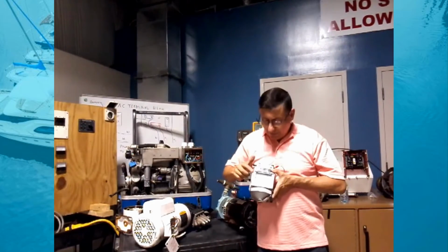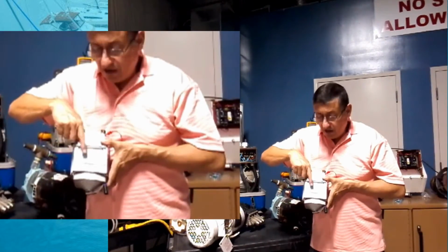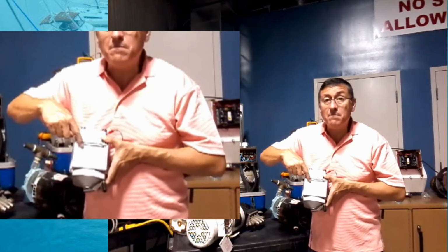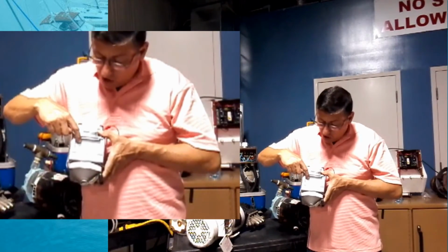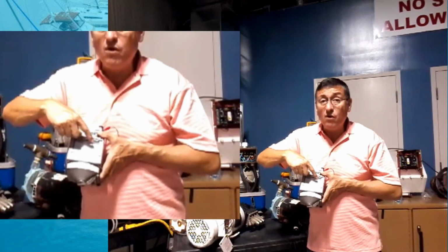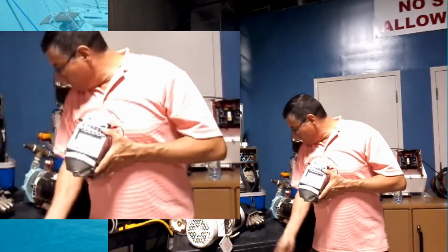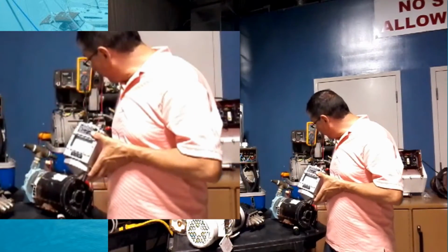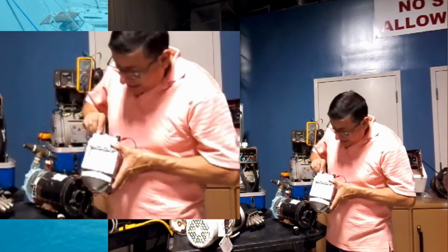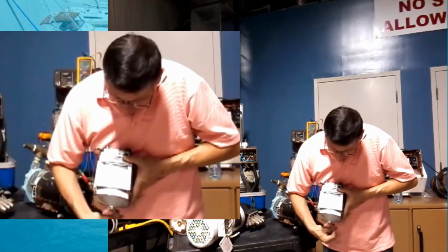Okay, we are going to check. They have 0 on this side, infinite on the other one, and they have the marks in megohms: 1 megohm, 2, 10, 20, 100, 200, 300, 500, 1000, and infinite. Okay, I am going to check right now in this equipment how much is the reading when I crank it. When I crank it, it stayed at 20.